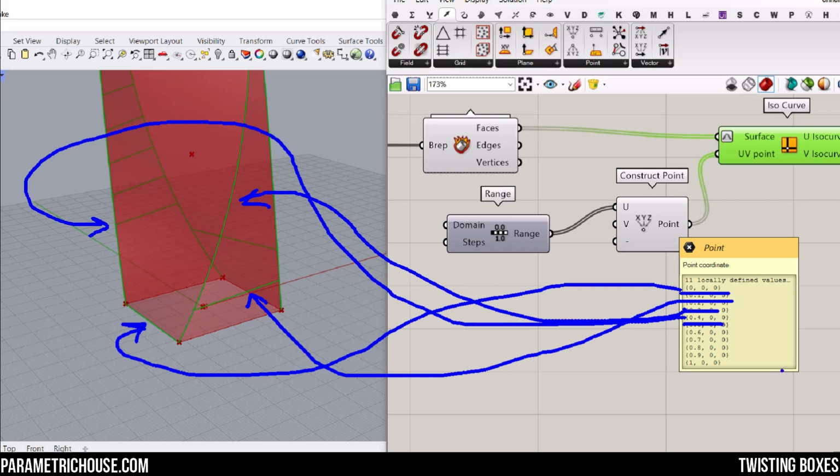Then, because we have the fifth and the sixth until the end, and we don't have the fifth polysurface, it's going to assume that all of this is for the last polysurface. This is a long list in Grasshopper, okay? Grasshopper, by default, is working on the long list. So how can we fix this?